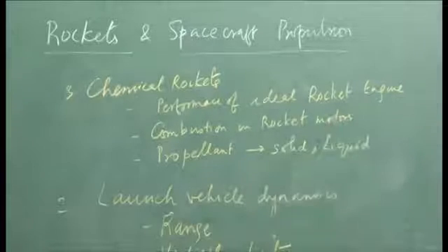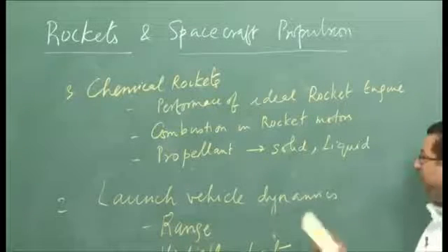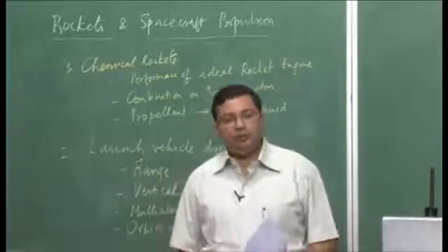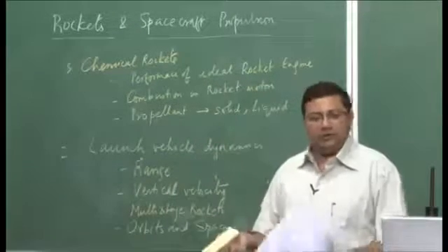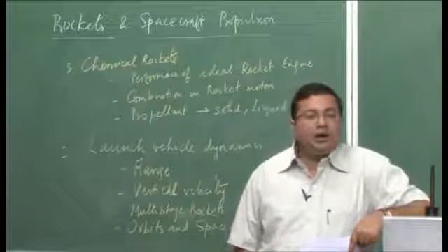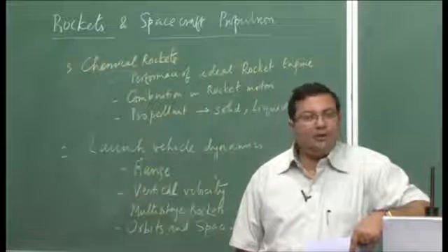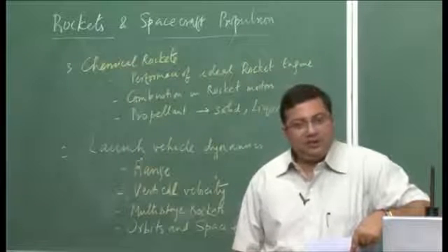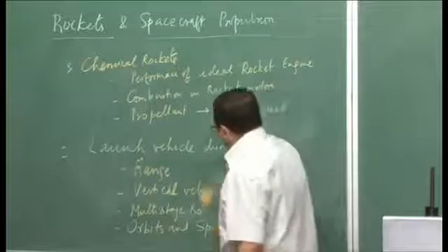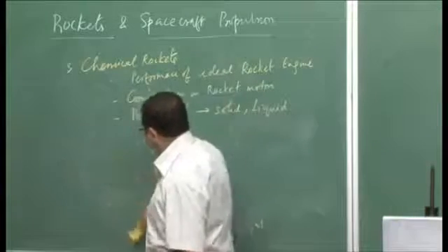Now, one of the subclasses of liquid propellant is cryogenic propellant, which are propellants that at standard atmospheric pressure and temperature are in gaseous state, but under very high pressure and low temperature they are in liquid state. So, these are called cryogenic fuels or cryogenic liquids, which we will be discussing as well.